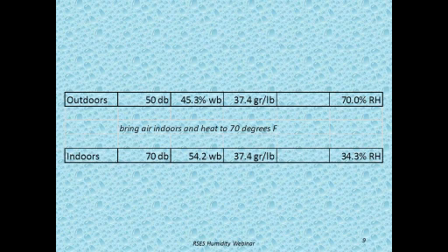We're going to look at 3 examples where we have outdoor air and indoor air at different temperatures. But we've kept the absolute humidity levels constant in each one of the examples. In other words, our outdoor air is 50 degrees dry bulb, and this is all Fahrenheit. 50 degrees Fahrenheit dry bulb is simply a plain old thermometer temperature. There's no humidity taken into account. And we also, for the outside air, have 45.3 degrees Fahrenheit wet bulb.